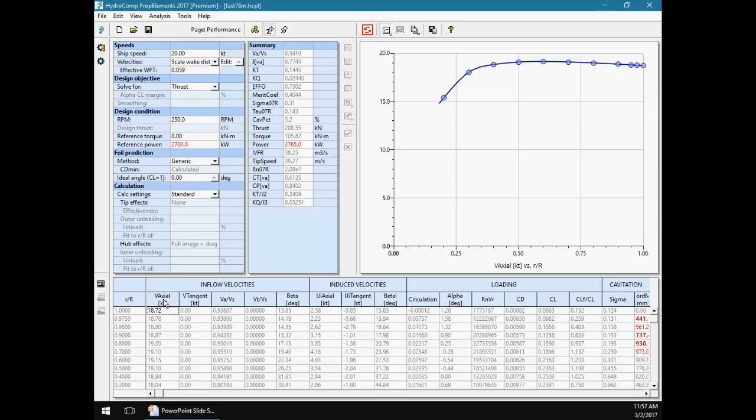So my mean velocities are going to be the same. But now you can see I have a variation in my axial velocities for the propeller. This is similar to what would be done in a multi-blade element design, where we would be taking the output of the forward blade and entering it in as the input for the after blade, with appropriate corrections for axial distance.